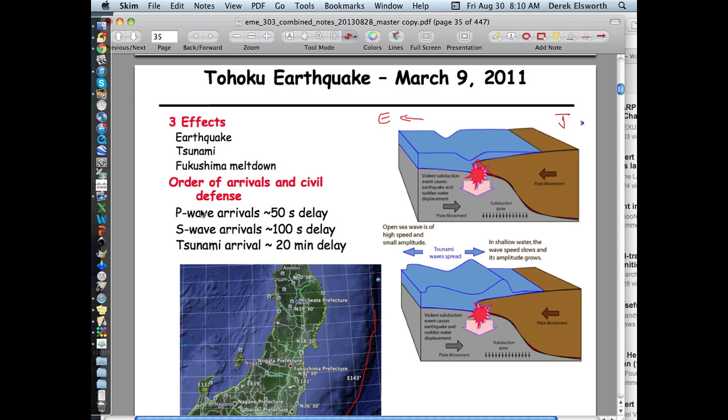And so if you look at these P-wave velocities, the P-wave velocity in the rock is something of the order of, say, 5,000 meters a second, if you use the correct modulus for rock. The modulus for rock is about 2 to 10, say 10 gigapascals. The S-wave velocity might be half of that, say 2,500 meters a second. And the velocity of the wave that's produced is something of the order of 100 meters a second.